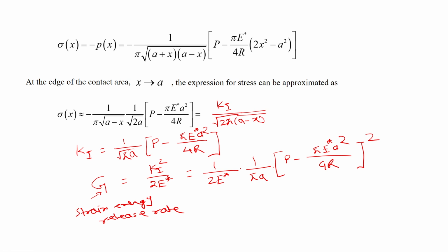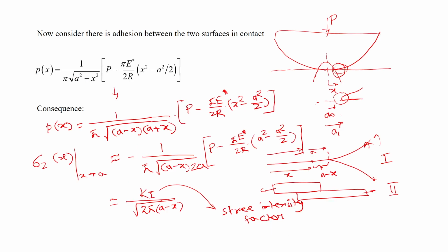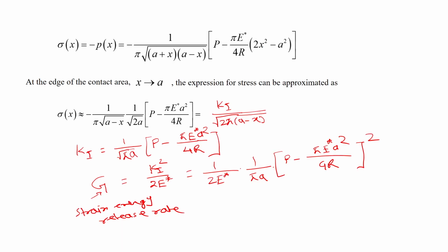So, that means this is the amount of energy that gets released when the crack propagates, right. And in our case, when the crack propagates, there are two new surfaces that form. So, the crack comes over here. Now there are two new surfaces created, and we know that from an interface, when two surfaces get created, that is basically the energy of adhesion, the work of adhesion.